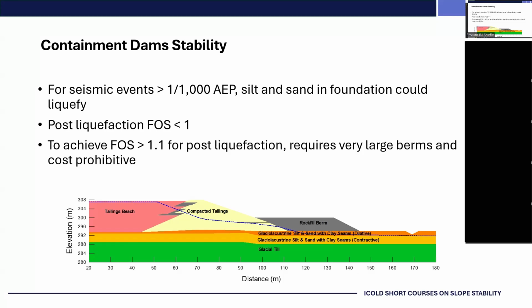We said during a 1 in 1,000-year seismic event, we do not envisage liquefaction occurring of these materials. You're meeting the standard of the day, but there's a potential that you could have a larger event occur, and this then could run away from you. And to handle that, you would have to build these large berms. And they made the decision to not build the berms. We need to be careful that we, as consultants, did not make that decision. They made that decision with our input.